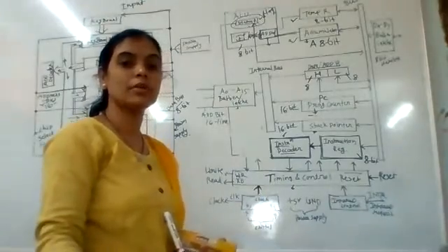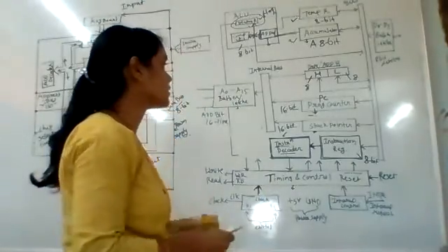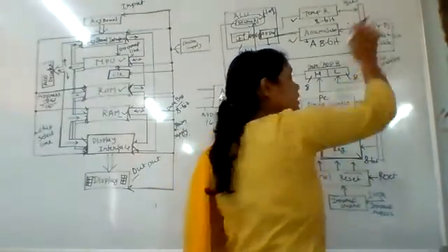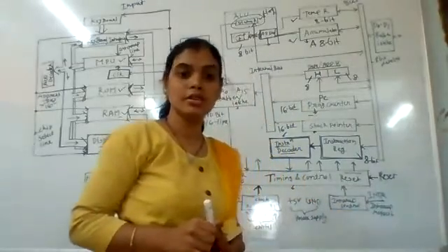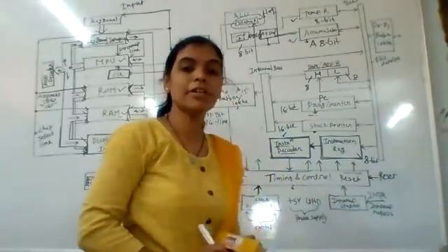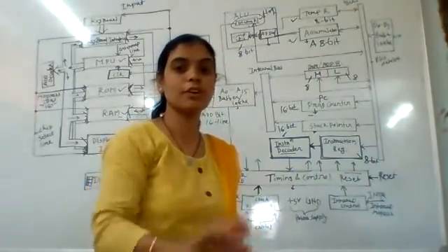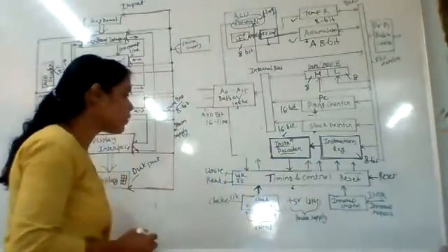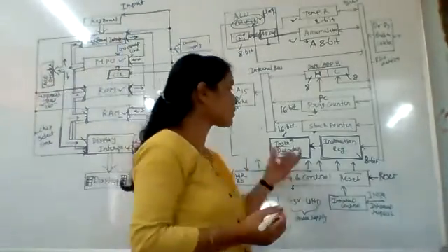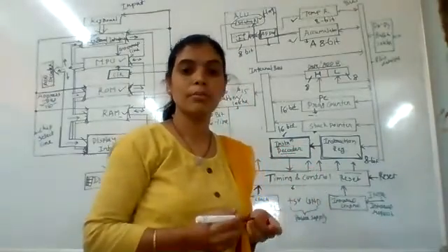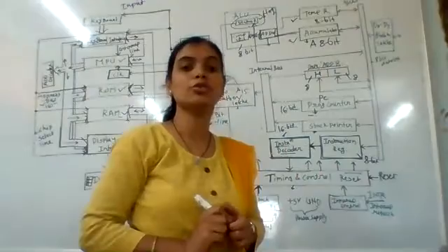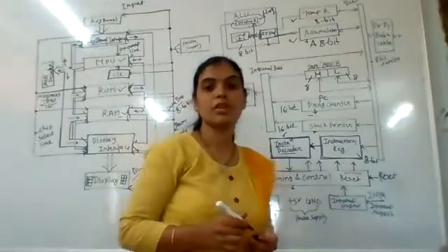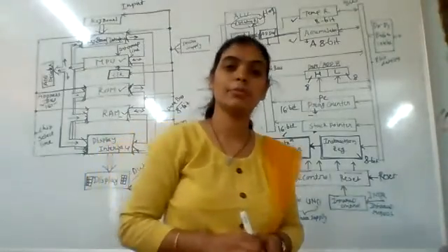The data bus is a group of 8 lines, identified as D0 to D7. These are the 8-bit bidirectional data bus lines used to transfer data between the MPU and devices. Next is the control bus, which carries the control signals generated by the MPU.